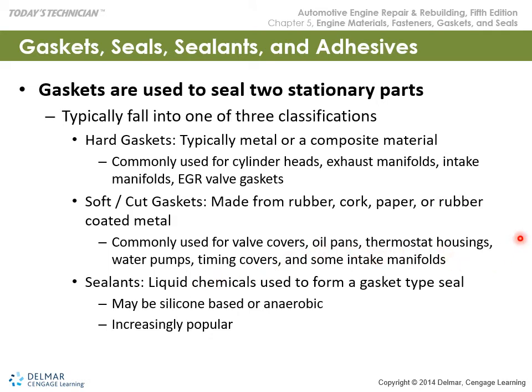But you have to use the correct gasket, and you want to save all your gaskets and O-rings that come out of the engine, and make sure that your kit that you have to rebuild the engine has the correct gaskets in it, not just size, but also material. There are instances where the gasket kits are shipped with either wrong or missing parts, so you want to make sure that you're checking all of these as you do your assembly.